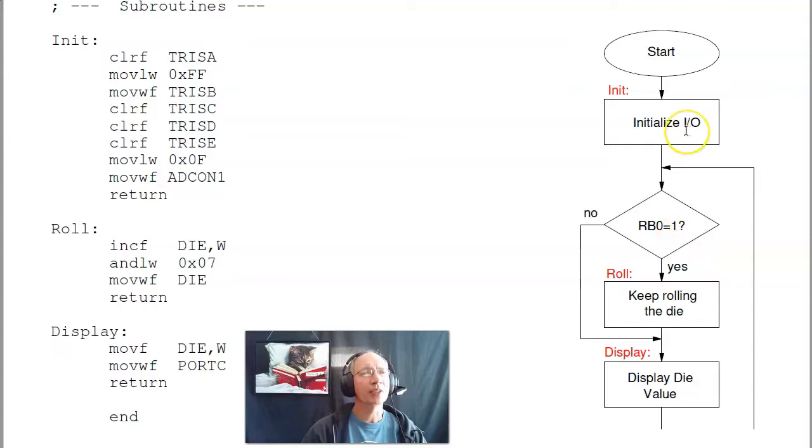You first get the I/O pins to work. That's what we did initially. Display the numbers 1, 2, 3, 4. Get it to count. Get it to count when you hit a button. Get it to display the count. Go in baby steps, and you can finish your assignments usually in less than an hour.